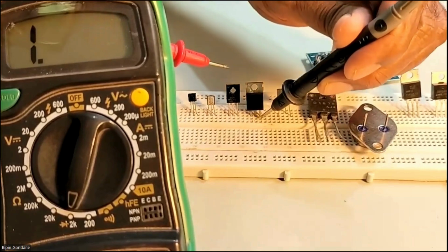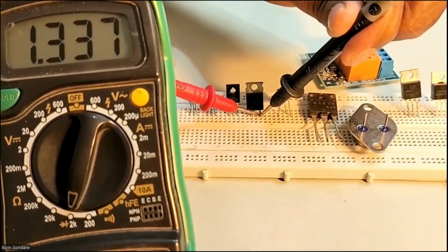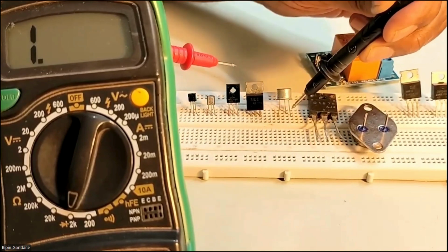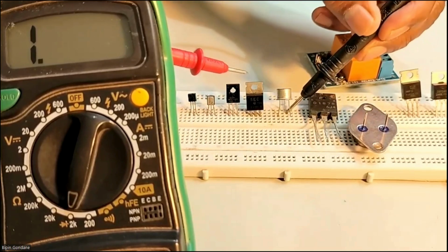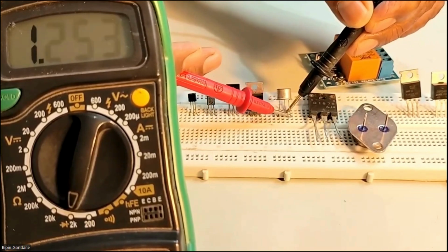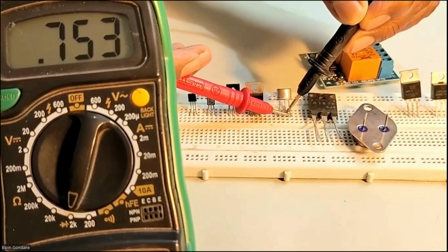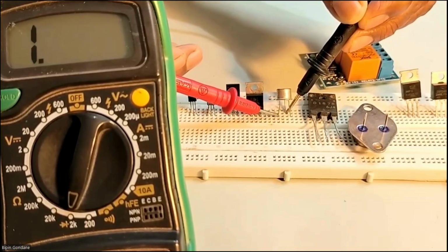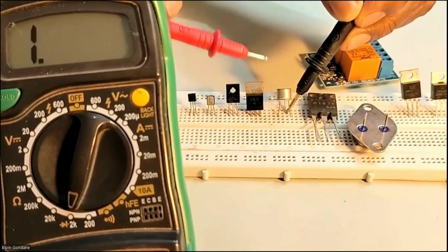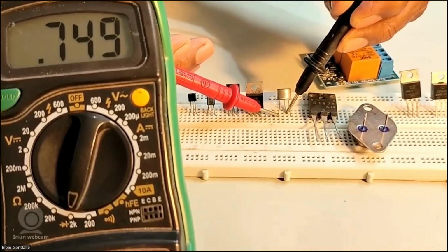Same thing here also. The number which is given on the transistor, accordingly, you will check this. Here, there is a BD series or metal transistor, this one. This is center base. So I told you this, when you go to industry and keep on working in the industry or testing, you will come to know. So center is base and both the sides it is coming. This is PNP, because the negative is on the base. So PNP.